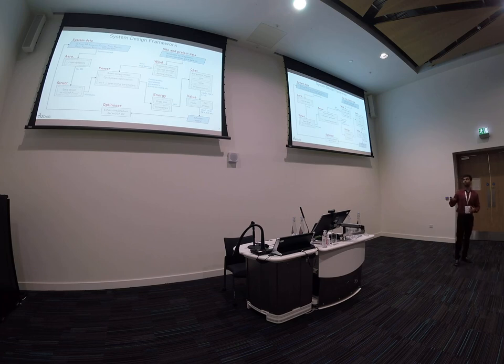I do not focus on the aerodynamic and structural evaluation of the kite itself, but I take the pre-evaluated results as a starting point to move ahead. For the kite mass scaling, we have a data-driven model, which is trained using mass data obtained from company prototypes, projected data, and also literature. It is a nonlinear function of wing area, aspect ratio, and the maximum tether force it can hold. The power computation model is a quasi-steady model. I will tell you about it in the next few slides.